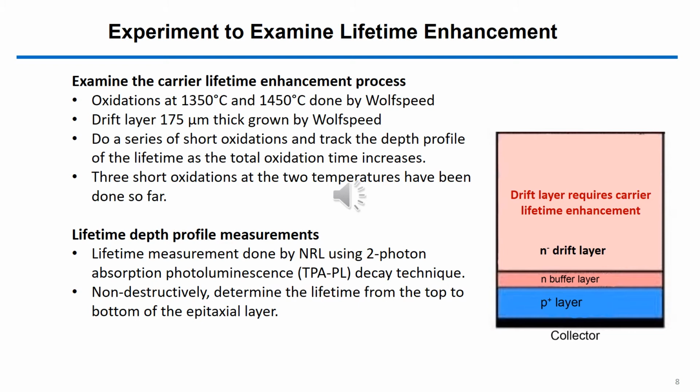The plan is to do a series of short oxidations so that we can track the depth profile of the lifetime as the oxidation time increases. The lifetime will be measured at NRL using a 2-photon absorption technique. It's non-destructive, and we can determine the lifetime at any position from the top to the bottom of the epitaxial layer.